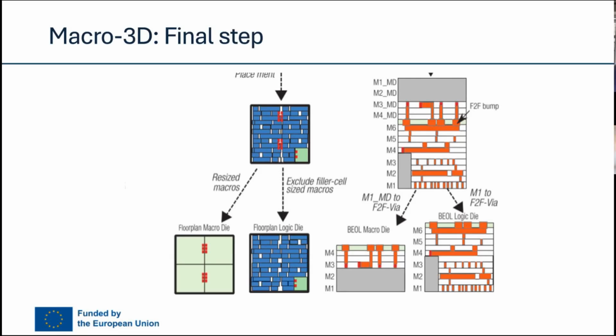The only limitation that we have is that the location of the macros which are in the upper part is fixed. The two advantages that you get with that is that we have a perfect definition of the timing, and also that we can use the complete stack for the metallization even if we are using a standard 2D tool.